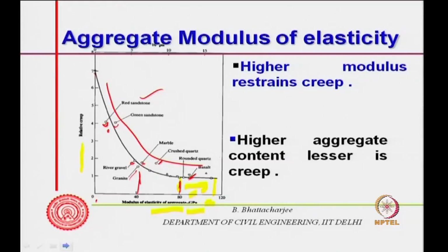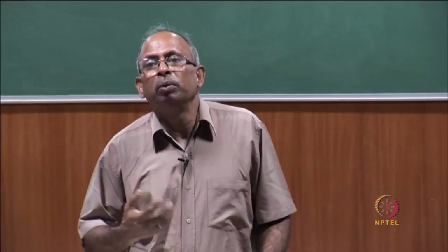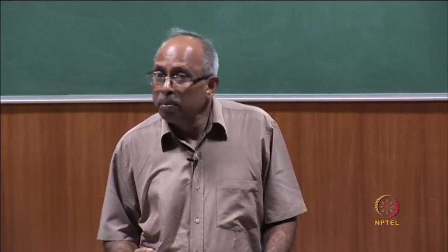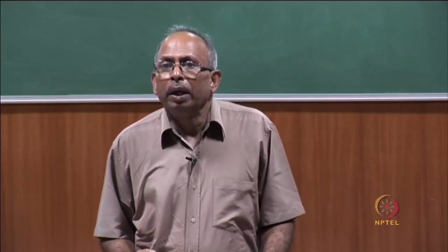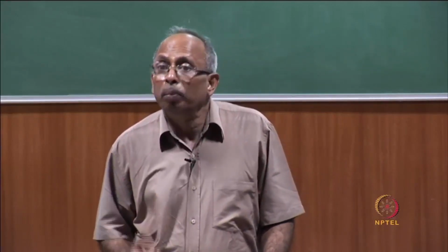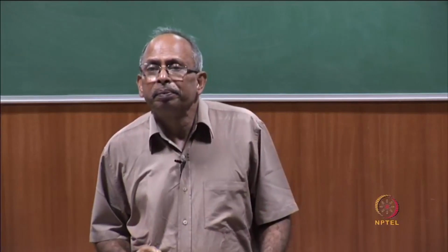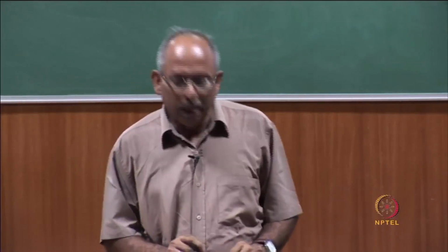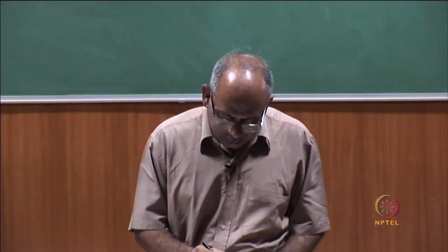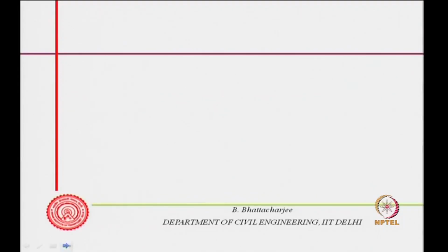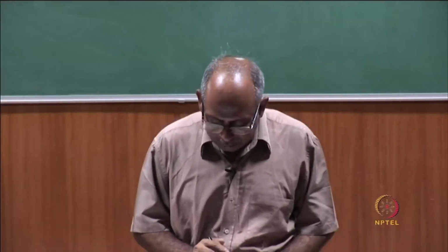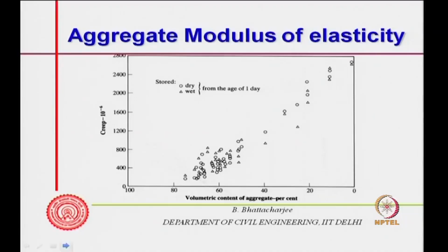Higher aggregate content, of course, will also result in lesser creep. It is related, because aggregate does not creep, it is the cement paste which is responsible for creep of concrete. Therefore, the more the aggregate content, the lesser will be the creep. This we can see in this diagram.